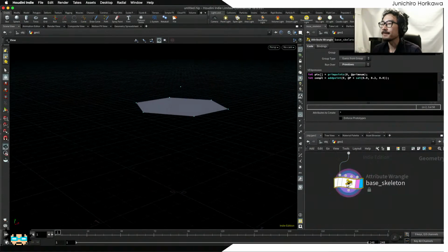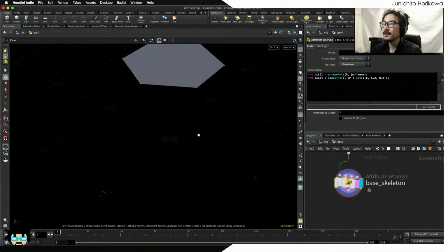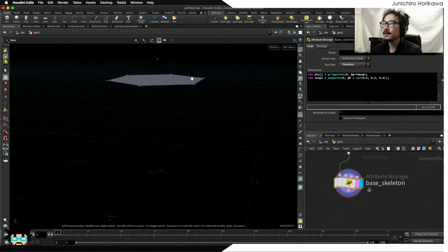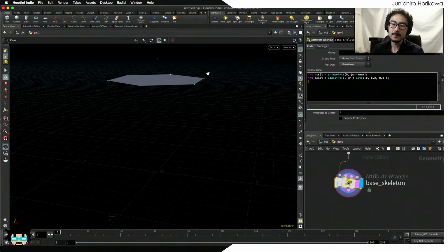Now the next thing I would like to do is to connect this center point with each of the vertices, and then go to the floor to create leg-like lines. Okay, so before doing that, I'm going to set the name for this point that I have just created, the center point, and later on I'm going to use that name attribute in order to define which point will be used as a controller for the inverse kinematics for KineFX.